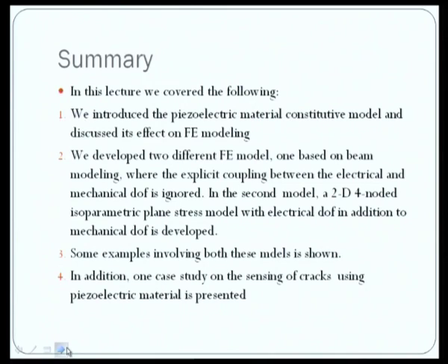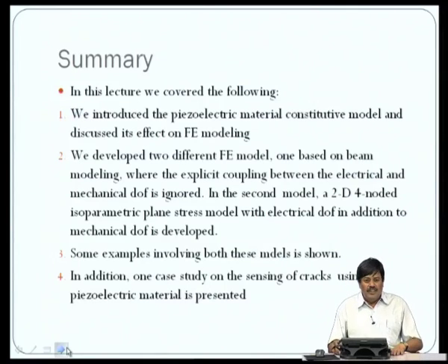So, let us summarize what we studied here. In this lecture we covered the following. We introduced the piezoelectric material constitutive model and discussed its effect on the FE modeling. Basically, the effect comes in terms of the additional coupling matrices, because of the additional energy that goes into the weak form of the equation due to the electrical field of the piezoelectric material.